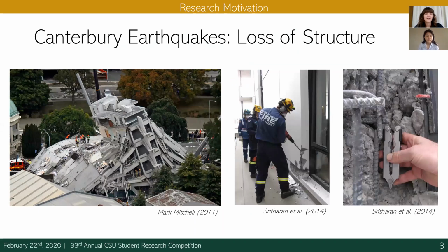The reason we care about lightly reinforced concrete structural walls is because they've behaved poorly in past earthquakes such as those that happened in New Zealand in 2010 and 2011. For these brittle, non-ductile walls, it isn't so much strength as it is drift capacity that is an issue. Many of the walls that performed poorly were characterized by three main components: low gravity loads, light steel reinforcement ratio, and no boundary elements, which means that there was no concentrated steel at the ends of the walls.